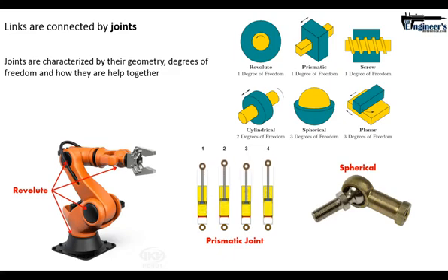And again, remember, a link is about having a controlled output. So these linkages that you select are very important in your mechanical design. Now, I mentioned the term lower pair. Let me go back and define that and give some clarity on what I meant by those six types of joints being a lower pair.